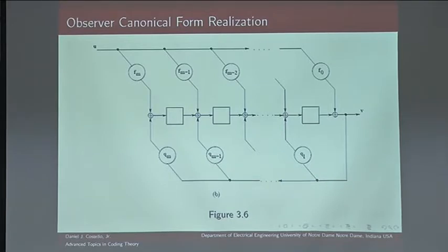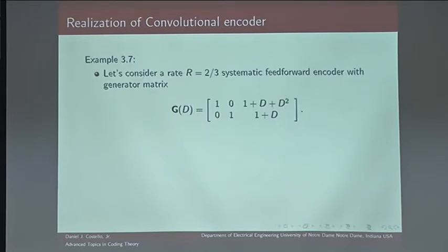And the encoding, the transfer function, is just a 1 in those cases. So there's no shift register, it's just a connection. So you need only one shift register then for the parity sequence. And that's easy to generate in this form. If you try to do it with the other form, it's more complicated.